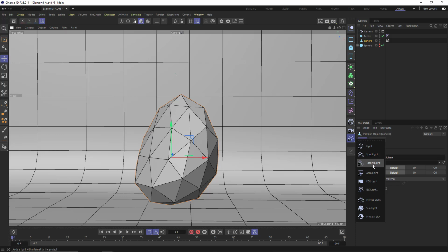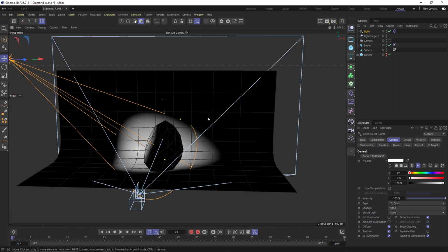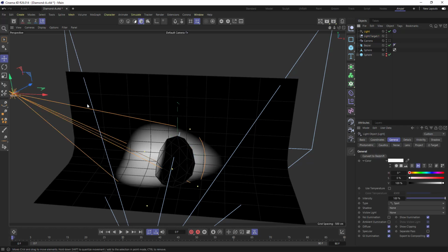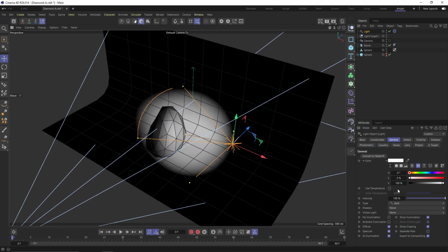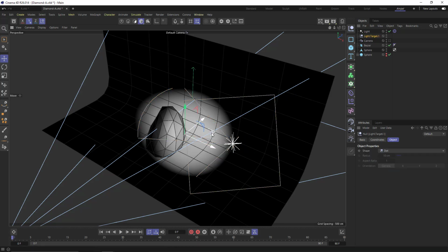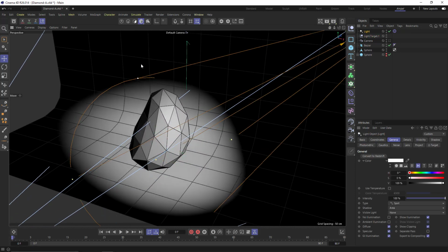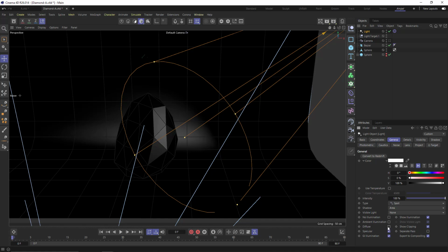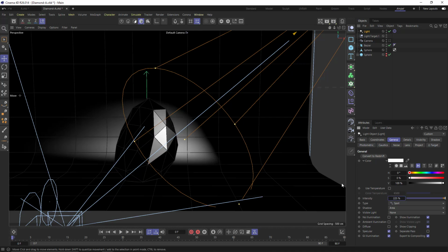Now we'll start adding the basic components to prepare for rendering. Lighting is the most important component, so we add a focused light with a target direction element or a center of light beam projection onto the diamond. We adjust the lighting from the right or at whatever angle you see fit. Then we deselect the diffusion setting to achieve a dark background and increase the lighting intensity to 225 to make the diamond appear strong and the internal refractions contrast.